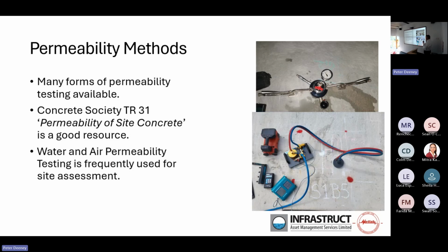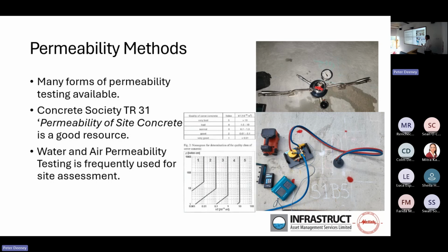As I've said here, this is the air permeability test kit from ProSec, the Turbine system. Again, better probably suited to drier concrete. So maybe when concrete is wet at the surface, it's not as easy to do. But this will actually force and suck air into the actual vacuum chambers. Based on that, it gives you a real indication of that surface zone, which really defends against penetration of aggressive substances. And it gives you an idea from very bad to very good quality concrete.